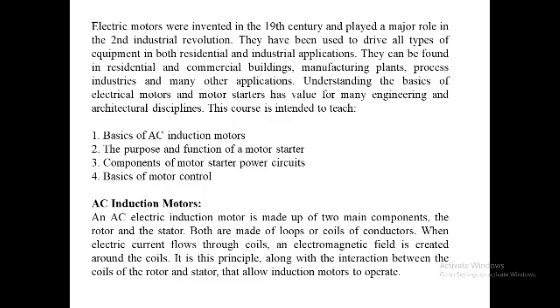A common motor design is a four-pole motor, which has a synchronous speed of 1800 rpm and a full load rated speed of approximately 1750 rpm.